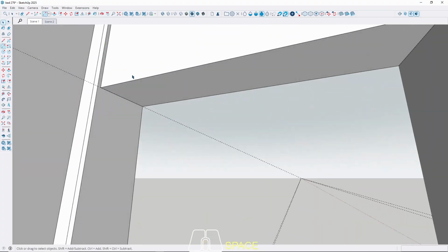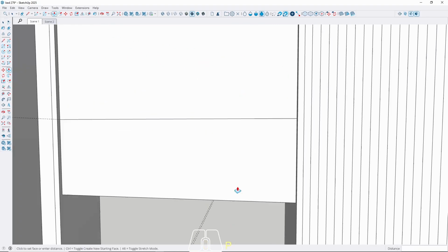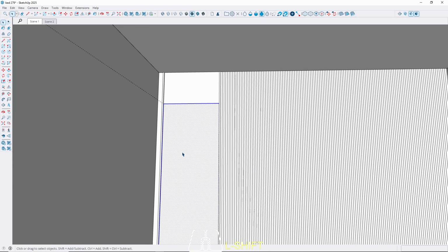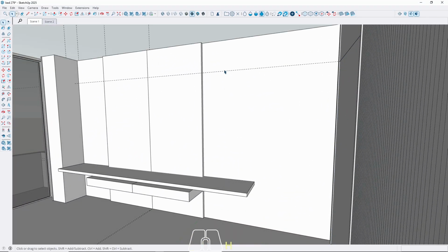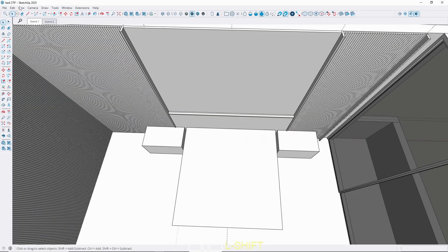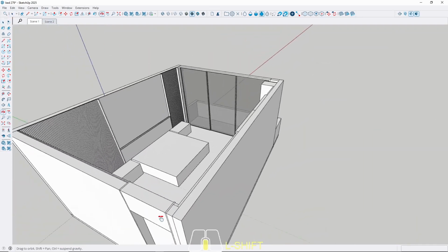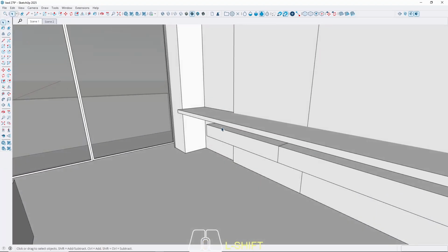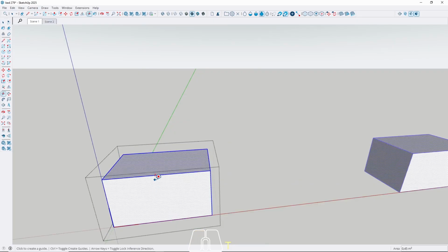Let's make a door. A door is usually 4 or 6 thickness. It's according to the structure and the hinge. But let's make it like this. Okay. We have a door. We already have design for every side. Oh, this one, the side table. Because we have a floating table design here, then we should make this side table floating also. I wanna use the same design language from this TV cabinet, so I wanna make it 5 centimeter thickness.